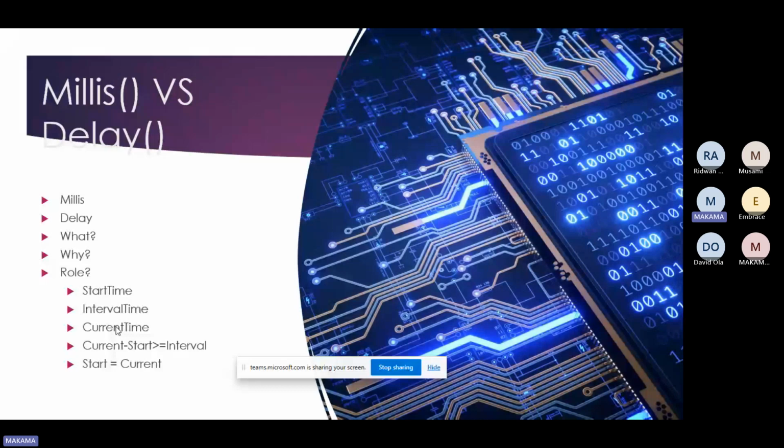So you need to develop some lines of code with the help of the start time, interval time, current time, then the condition, then the assignment. The way it works is that you need to set your start time. At what time do you want to start performing the task? The interval time: after what amount of time do you want to be repeating the task? Maybe only an LED. You want to turn on an LED after every 0.5 seconds, which is 500 milliseconds, right? So you need to specify that. You need to store the active time of your microcontroller in a variable called the current time.